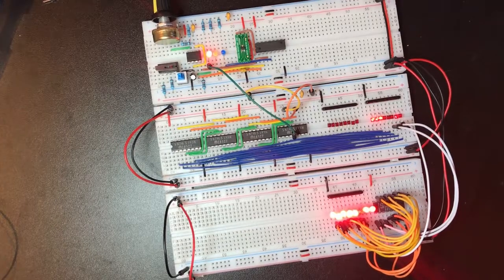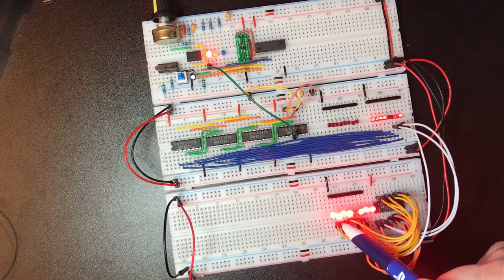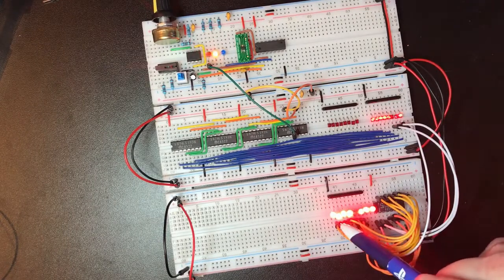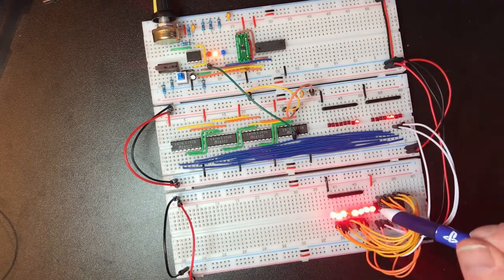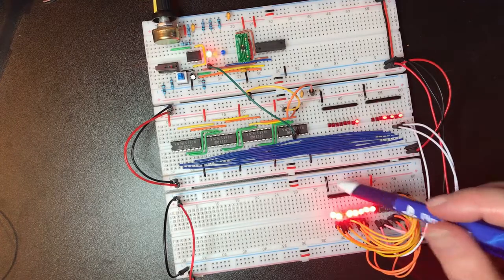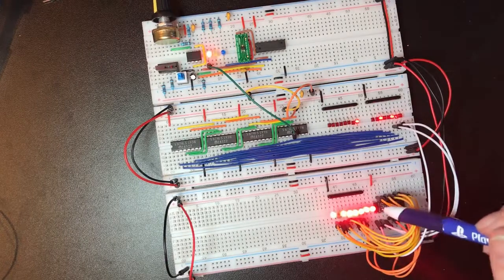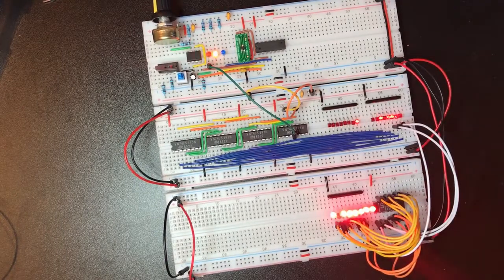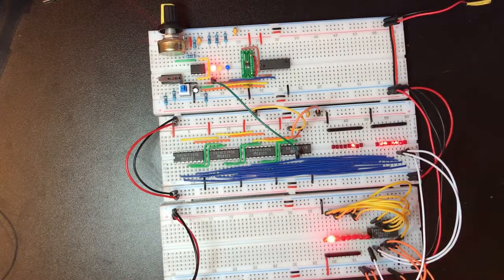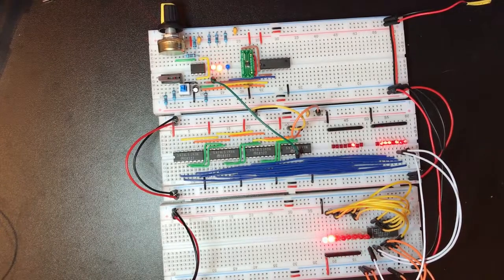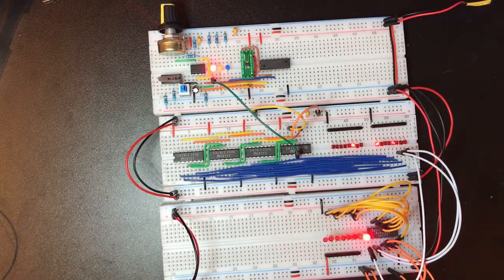Okay, this is a little bit non-obvious to look at, so whilst these lines are active low, I'm going to swap these LEDs over, drive them off the 5-volt rail and move these wires up here, so then the LEDs will come on when they're selected and it will be a little bit clearer. Okay, so now the LEDs are coming on when the lines are selected, so that's a little bit easier to look at.